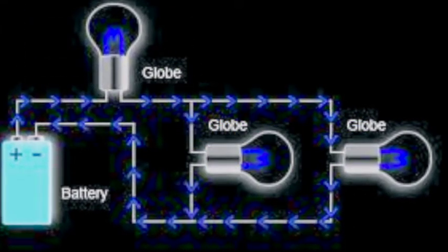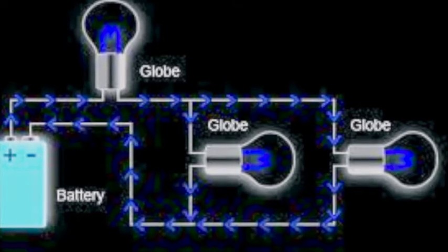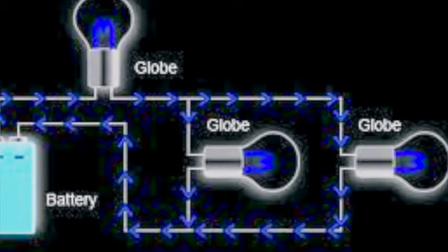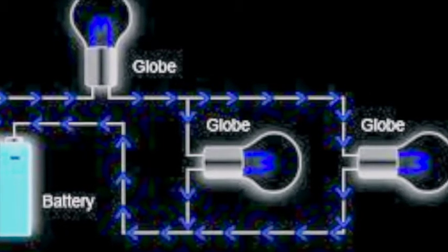Parallel circuits. The voltage is the same on every parallel branch. The total current is the sum of the currents in each separate branch, which equals the current outside of them. The equivalent or total resistance of the group of resistors is given by the equation.